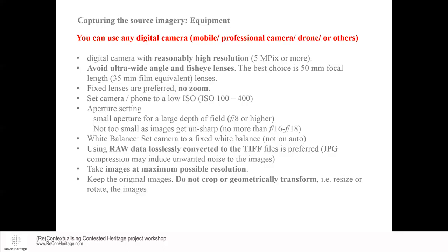And then in terms of general setup, the same rules for good photography apply to photogrammetry. You want good photographs to get the best result from your 3D modeling. So you want low ISO if you can set it. Obviously with a phone you may not be able to. So anywhere between 100 and 400 generally gives you low noise. You don't get lots of grain, which causes problems. So that usually is a good enough setting. And if you've got plenty of light, that's not a problem.